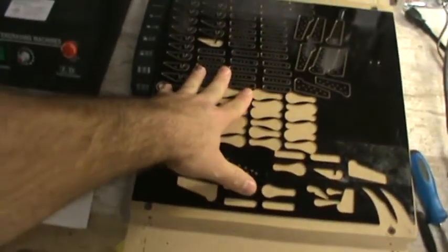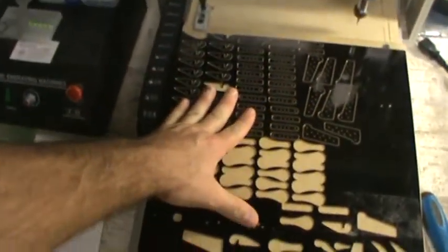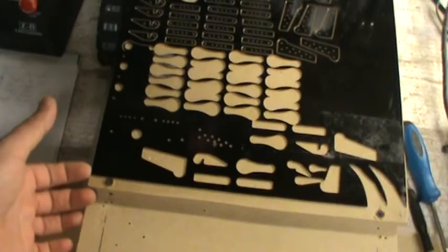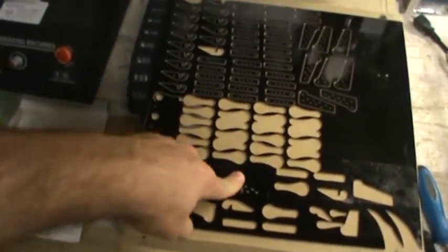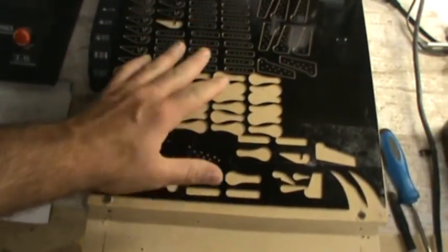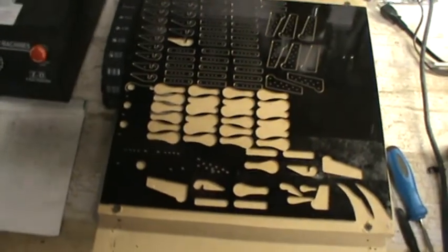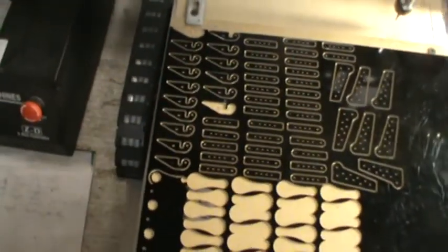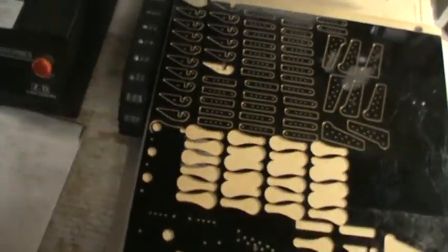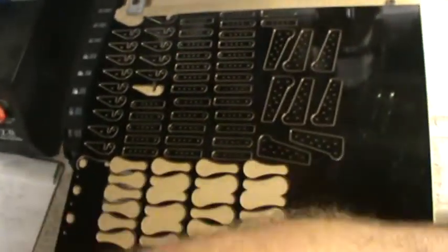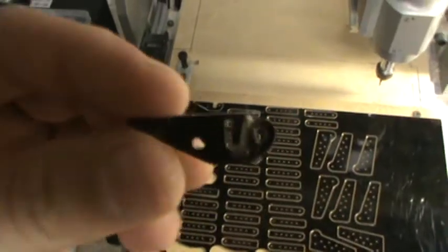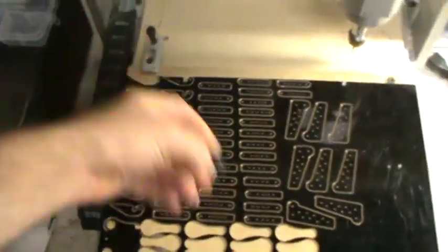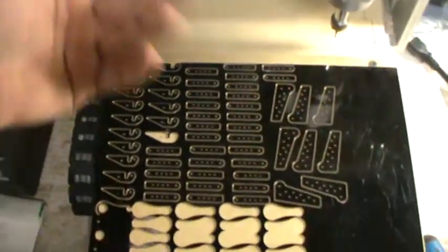Let that dry for a few minutes, and then I stuck the material straight to it, and you can see it's on there nice and good. I did not spray the back side of the material, just the spoil board. That way you can get it off semi-easily. You can see a couple of the parts have already come off, which I've got floating around here somewhere. Here's the one at the very top that came off just because the bit kind of pushed it out of the way.